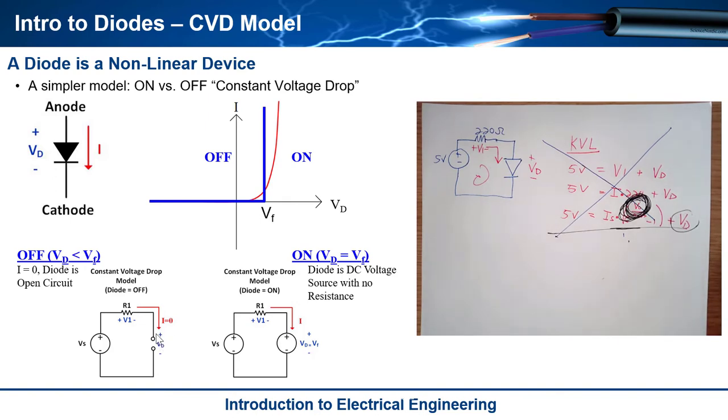That means that you can replace the diode symbol with an open, and you know that there's no current flowing through it. It can certainly develop a voltage. It does have a voltage on it, 1 volt in this example, but it's not on. So that means there's no current, and then that allows you to solve for a whole bunch of other stuff in the circuit. Like, for example, if there's no current through a resistor, there's no voltage across it.